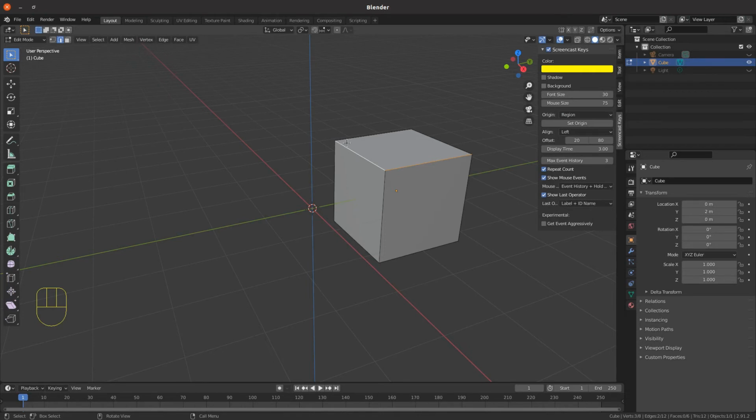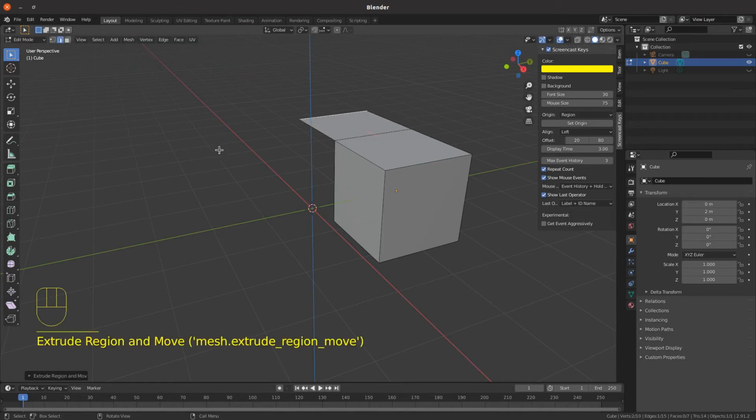active edge. And again, we can extrude edges, so we'll press just E, and this doesn't have a face normal direction, so it won't extrude perpendicular to anything. So it's effectively extruding freely from the position it was originally before you extruded. And you can tie that again to an axis by selecting, I'll go X, minus 2, enter, and that will drag out a complete face with it.